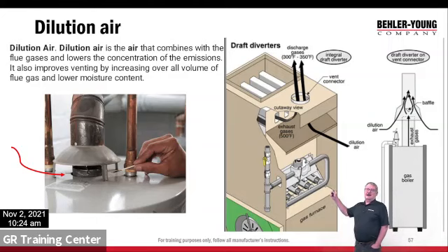Now, behind me here is an old furnace. And you can see at the top there where the cutaway is, it says exhaust. Okay, that's the outlet from the heat exchangers. So that's the 500-degree exhaust gas coming off, products of combustion. And then you can see the front here where it says dilution air is open to it. So now it's drawing house air, it's mixing with the exhaust air, lowers the flue gas temperature. You can see it about 300 degrees, lowers humidity, and aids in venting.